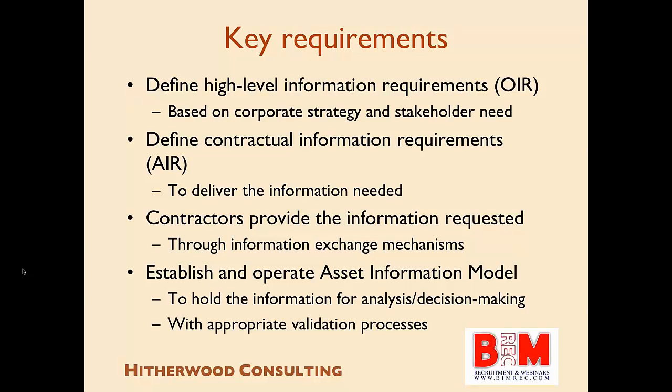The contractors are on the receiving end of these information requirements, and they get the contracts which define the work that they're being asked to do and which they will have priced. So they then have an obligation to provide that information back to the asset owner or operator, and that is done through a series of information exchanges. We've tried to use as much of the same principles and language that people are getting used to in project BIM in this way of defining asset BIM. So information exchanges are there as part of the contractual mechanism to move information backwards and forwards between individual contractors and the asset owner and operator.